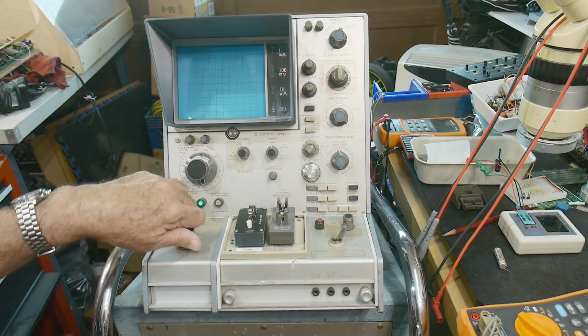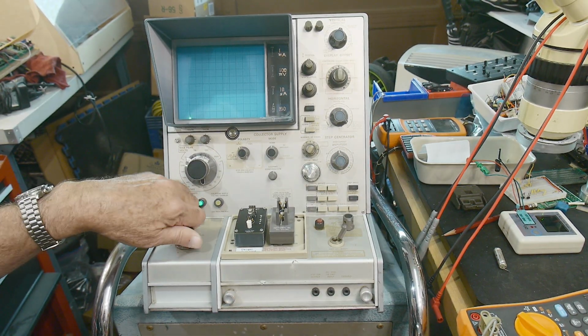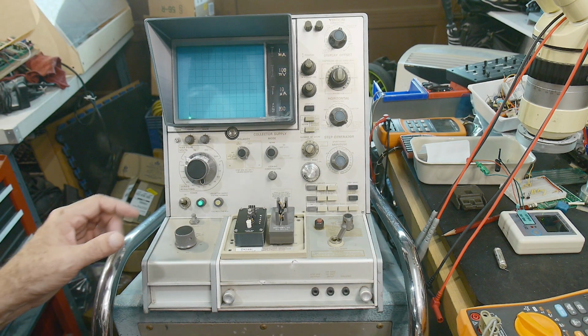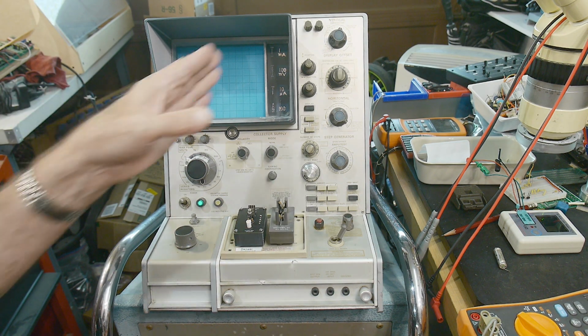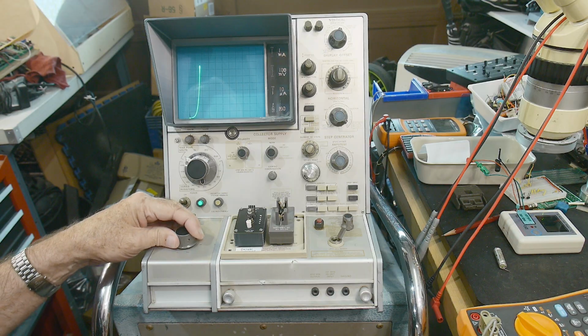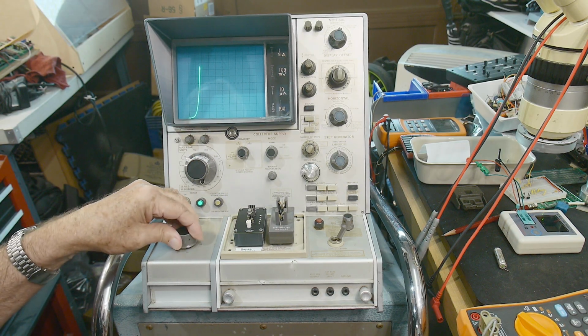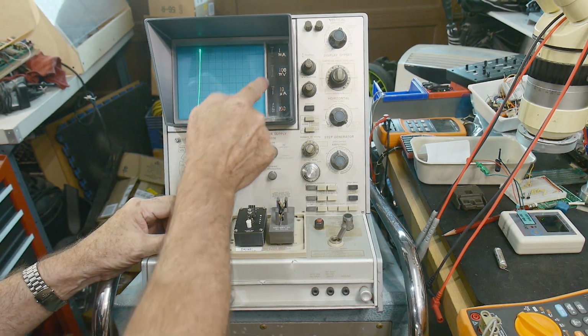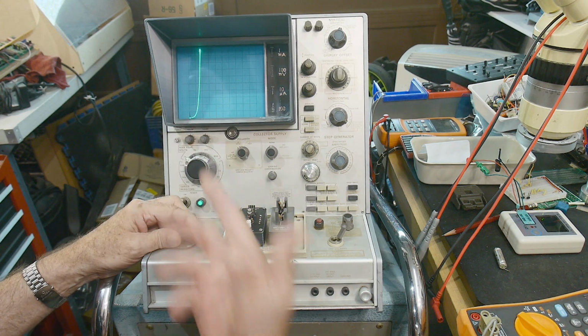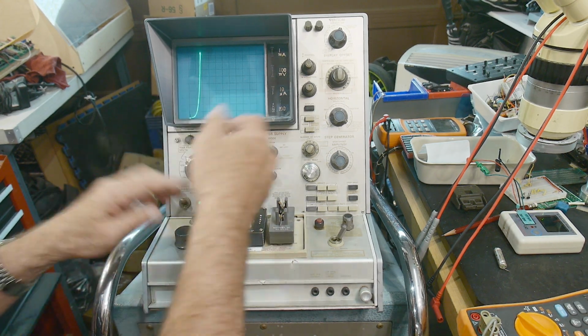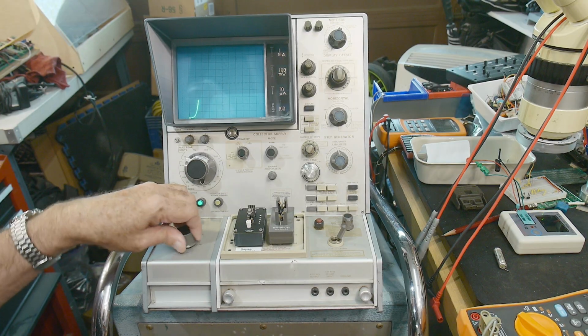So that's what a diode does, okay? So a diode has a curve here. And that diode had about a 0.6 volt turn-on voltage, right? Here's another diode, and it has a much smaller voltage. It only requires maybe 0.2 volts to turn on. That's a Schottky diode. So different diodes will have different curves, right?